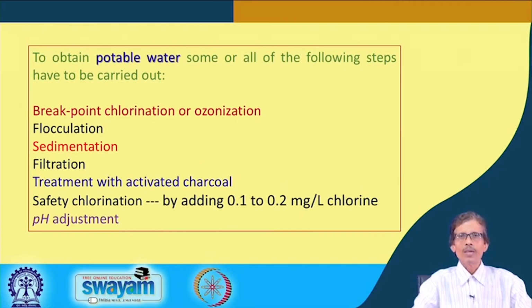If we find that the pH of the water is on the acidic side or the basic side, accordingly we have to go for acidification or addition of alkali, such as sodium hydroxide or potassium hydroxide, or sometimes a very dilute solution of ammonium hydroxide, to change the acidity.